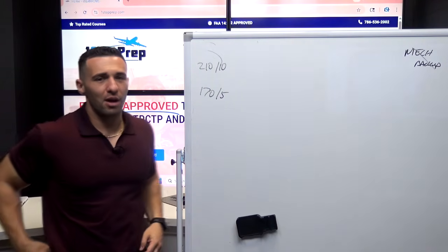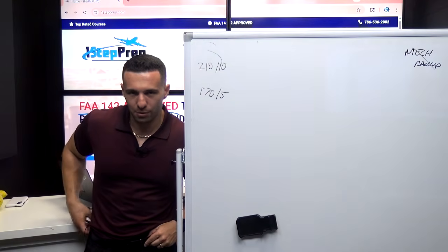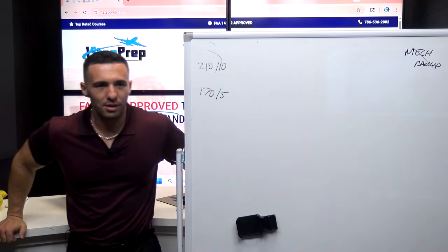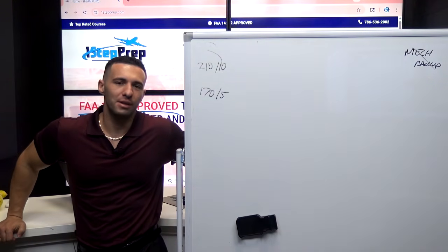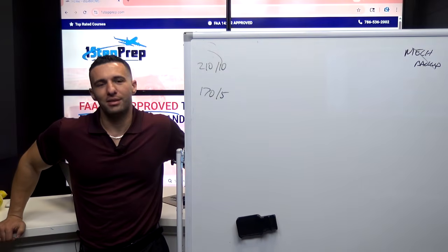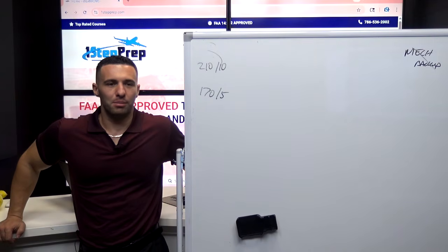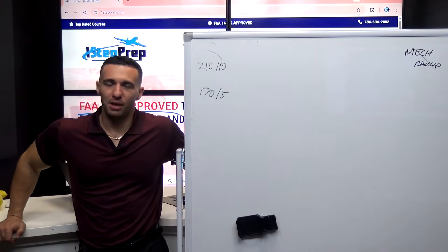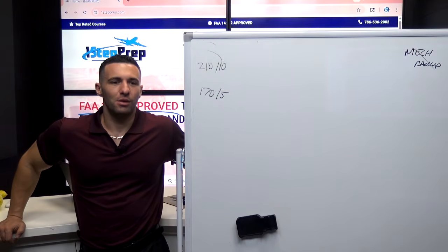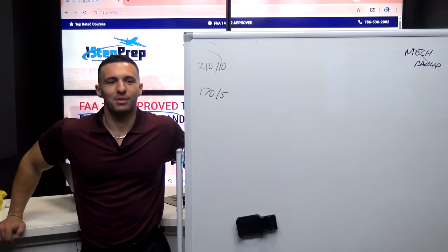By the way, that happens a lot, especially here in Miami. Miami's full of freighters, 747s and MD-11s taking off. They're super heavy, and there are speed constraints they can't comply with for whatever reason, so they just get speed relief. But either way, I think either way is fine. I always teach flaps 2 as the sweet spot for energy management.